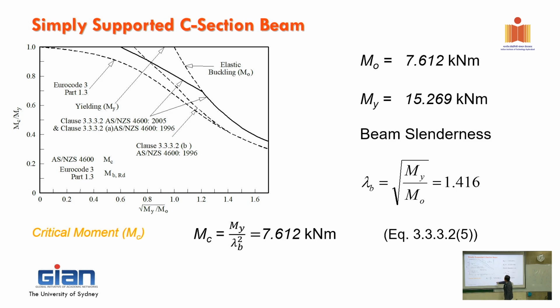Okay, so all depending on lambda. Lambda depends on M_o and then M_y. And remember, coming back to the other equation where you have M_o increasing significantly, then lambda reduces significantly. So it means it's going to the left. And when it's going to the left, the strength gets to what? It means that now it's equivalent to the section capacity.